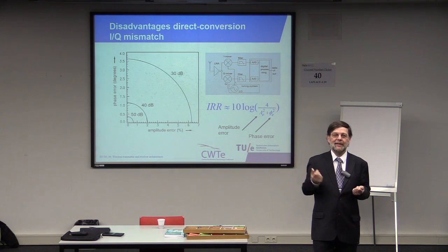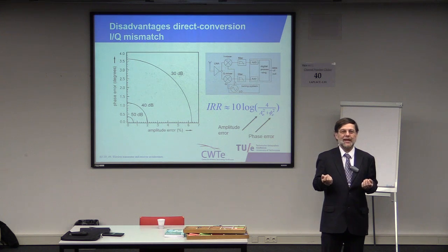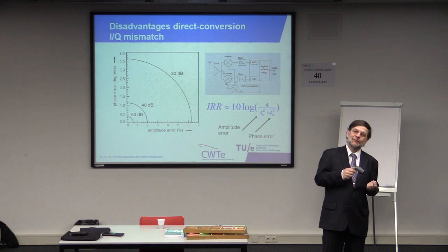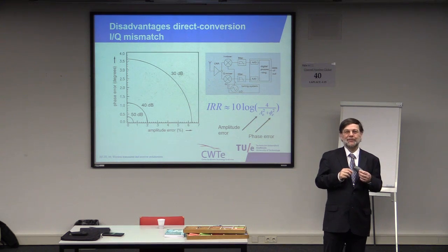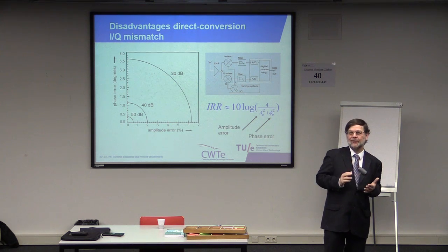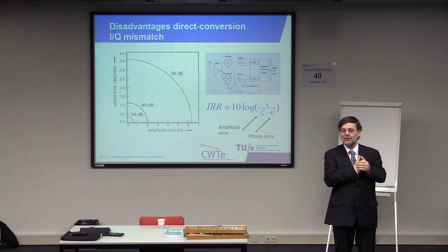Now, if you ever look at the cable in the lab, and especially the way that most students deal with cables, then even the accuracy with which you screw the cable connector onto the plug can easily change by more than 60 micrometers. If you turn a little bit stronger, then already you get the cable to be shorter by more than the 60 micrometers.